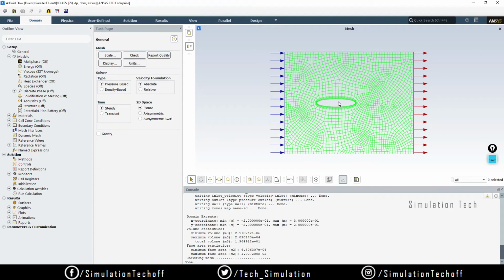When you use keywords like inlet, outlet, and wall in the condition names, the Fluent environment will always recognize those keywords. That is why it shows the arrows: this is for inlet and this is for outlet, and wall is assigned the brown color. Usually that is not shown. Fine.